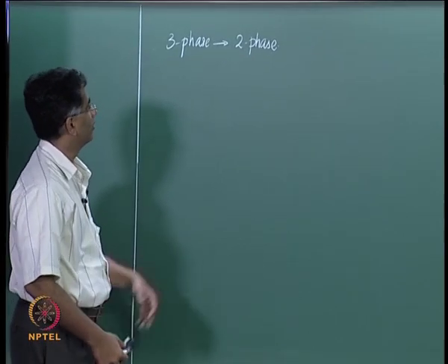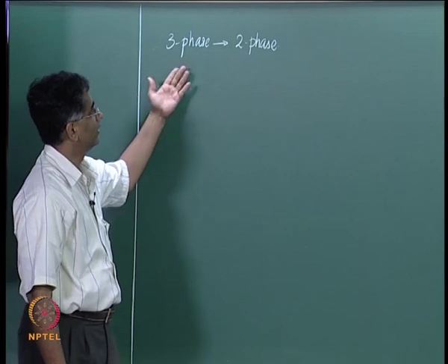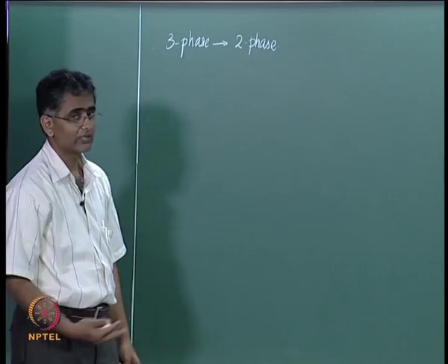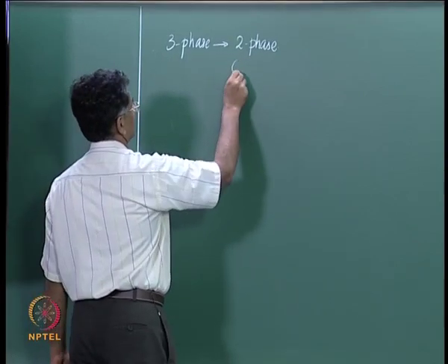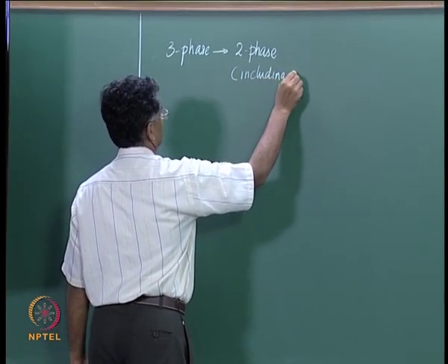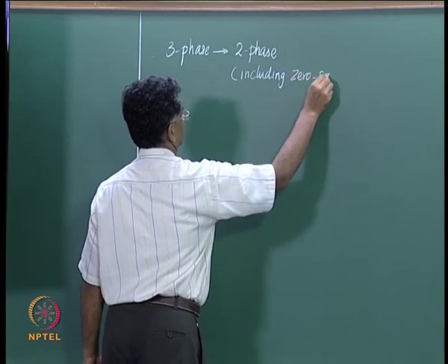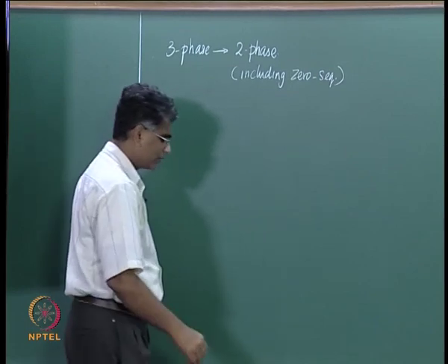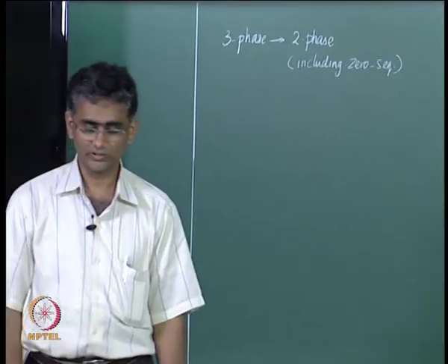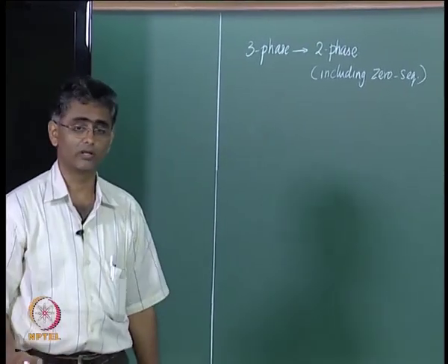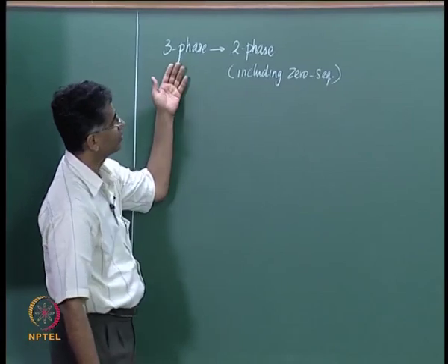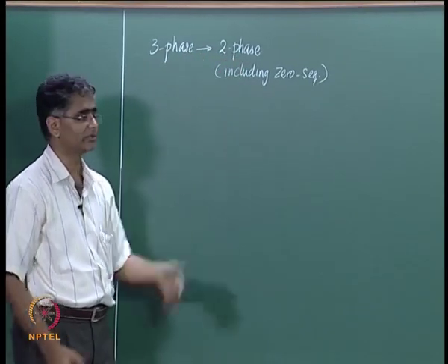We have seen the form of equations in the 3-phase case, and we have seen the form of the equations in the 2-phase. Needless to say, the two-phase description also includes the zero sequence component, which, as we said, for the most part is not there in a 3-phase machine if the system is operating in the normal way. So, let us look at the input variables themselves.